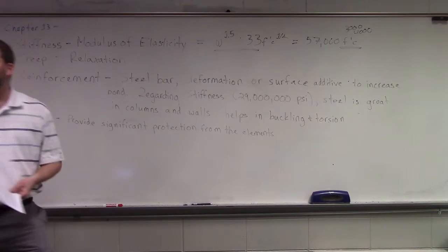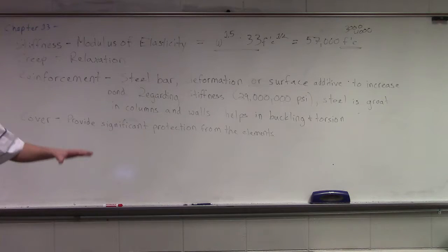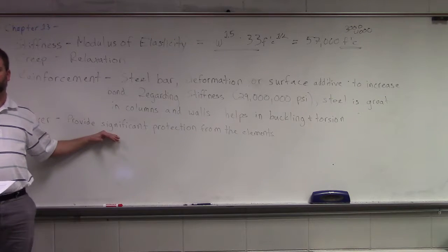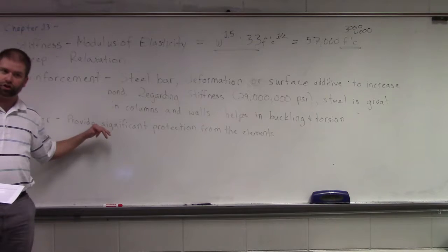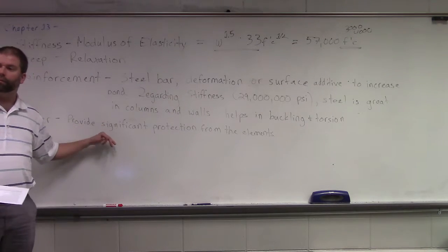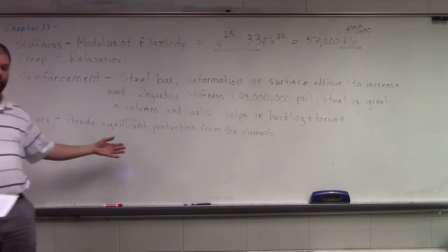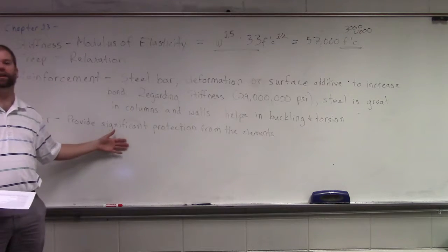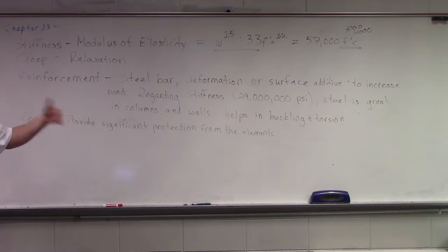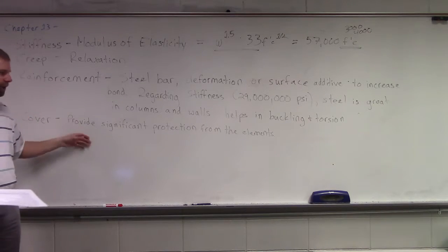So there's another thing from an engineering standpoint. Materials engineers need to be aware of not just that we provide sufficient cover, but that we are able to reduce the porosity of our mixture sufficiently so that we don't allow migration. There's a lot of testing that we do on mixtures, on any additives, before they get released to the public for common use.